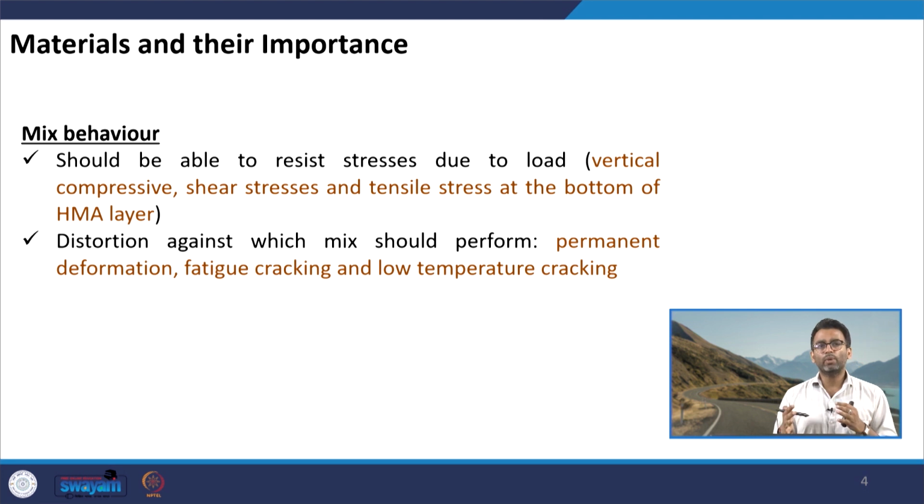Now, the final mix which is produced by mixing these aggregates with the bitumen, the aim is that it should be able to resist stresses due to different types of load. The load can be vertical in nature, or it can be compressive, there can be shear stresses, there can be tensile stresses at the bottom of the HMA layer, and we want that our mix should be capable of resisting